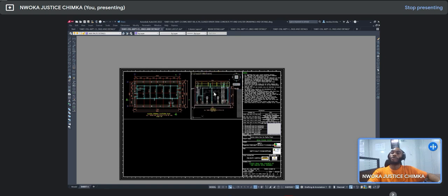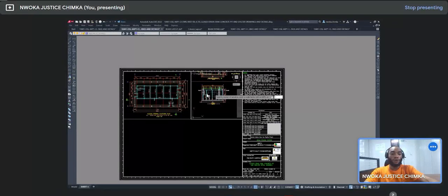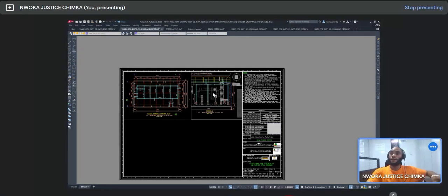All right, so I'll just go right now and then type Z, enter, 1 all over 35. So 35. Okay, 1 all over 35. Yeah, XP, and press enter. Okay, now this is why 35 is because 35 is the scale I use when I'm drawing this my plan here. So once you do that right now, I type PX to go out from that environment.